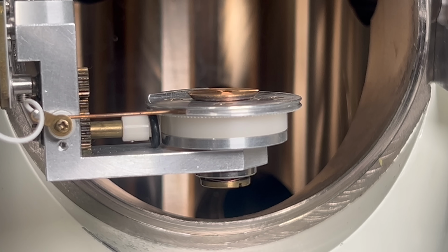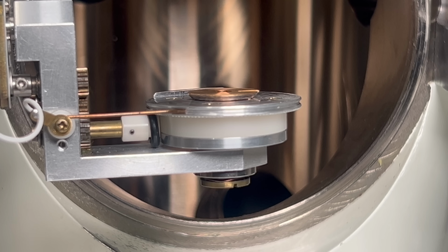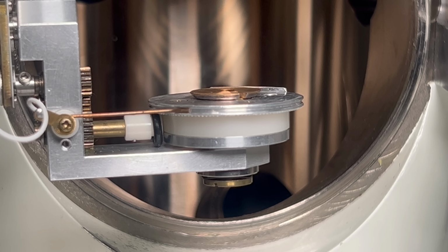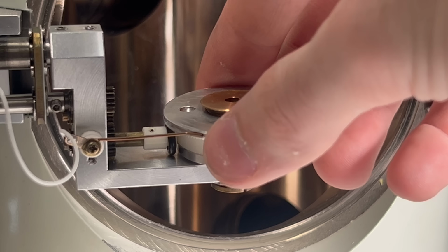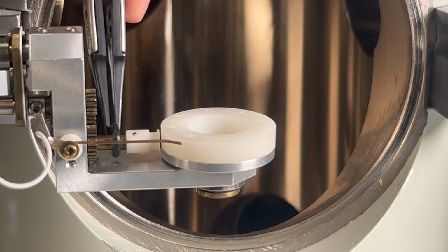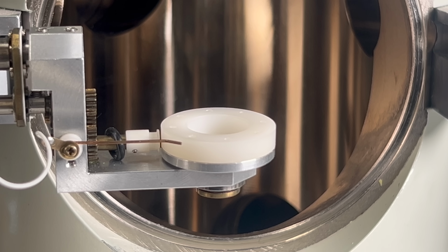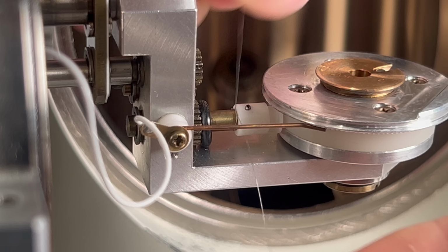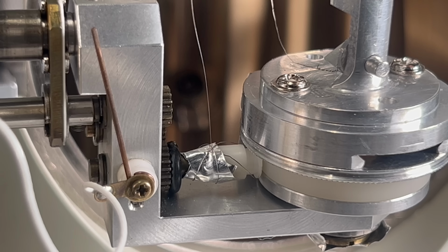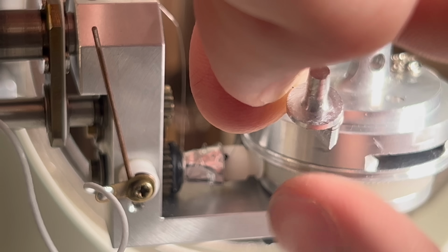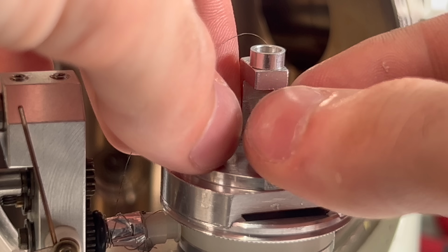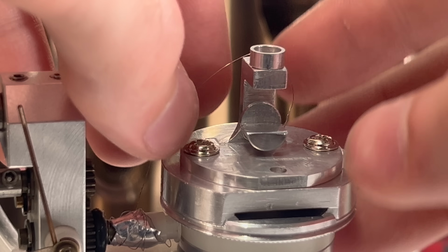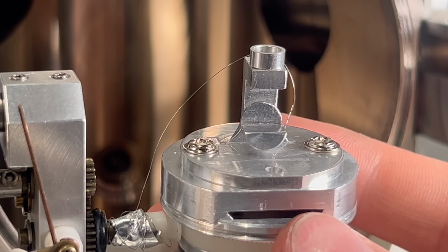I think I have an idea. If we look at the sample stage, we can see that the knob that rotates the stage is connected to this little shaft here that spins. Let me see if we can't use that to our advantage. If I disconnect the O-ring that drives the stage, then twisting the rotation knob will only rotate the shaft and nothing else. If I then wrap some tiny metal wire around the shaft, then I can create a little wire reel. If I connect the other end to the mirror, then hopefully, when I spin the external knob, it will rotate the shaft, which will pull on the wire, and that will change the angle of the mirror.